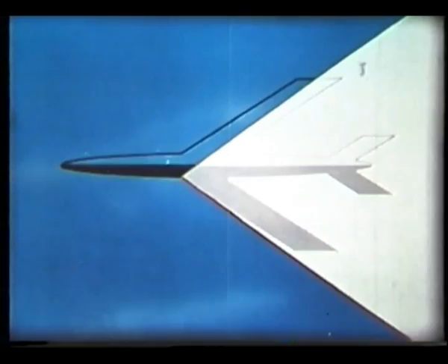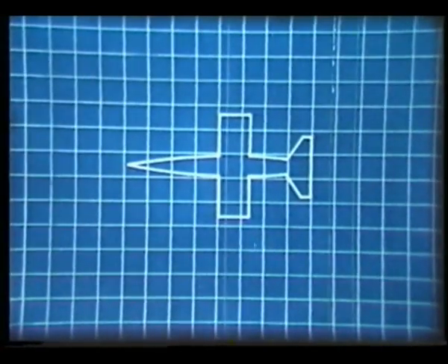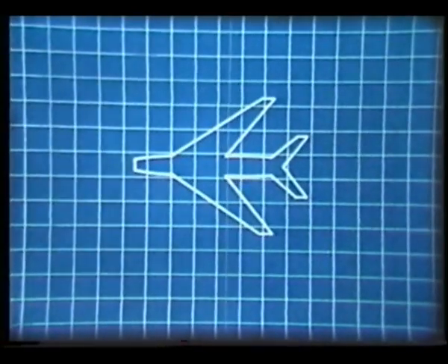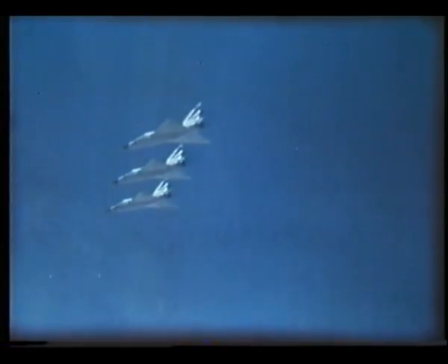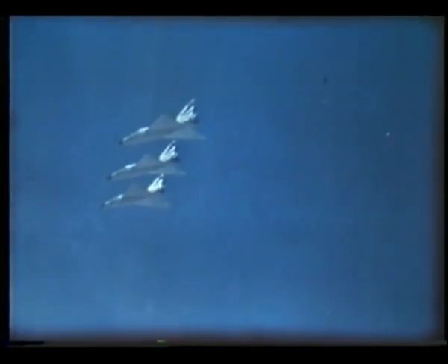But there are limits beyond which the aircraft becomes difficult to handle, both at low and at supersonic speeds. So the choice is between straight wings, usually short and of low aspect ratio for sufficient strength, or highly swept, or delta wings. What decides the plan form of a particular supersonic aircraft? It's a compromise between many factors, a very important one of which is supersonic drag.